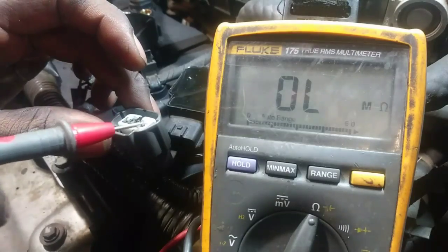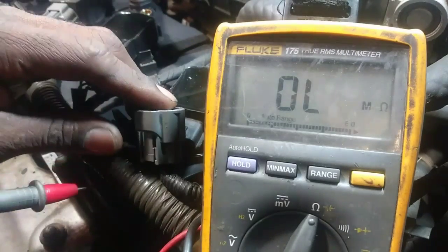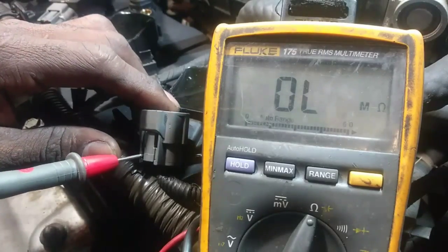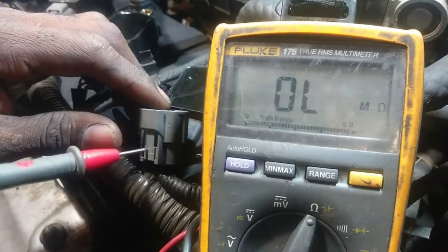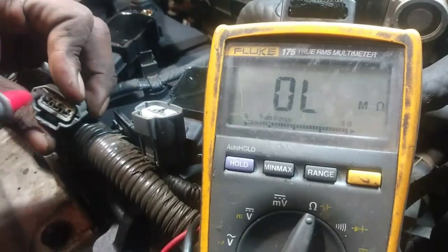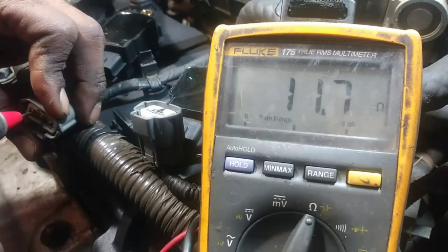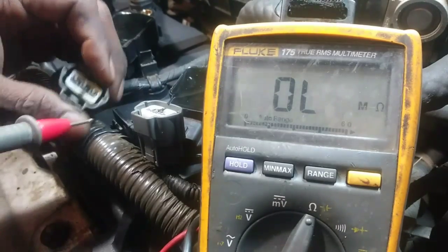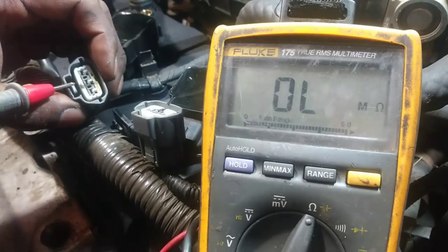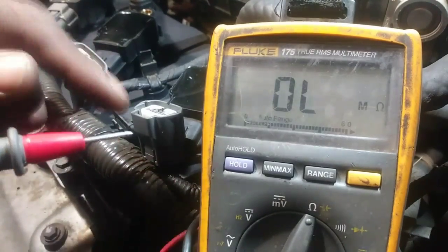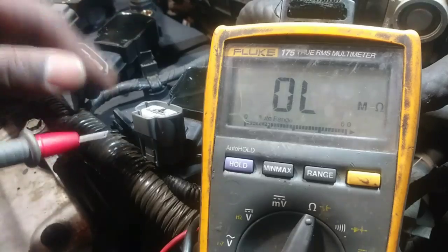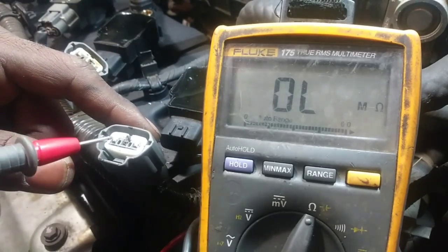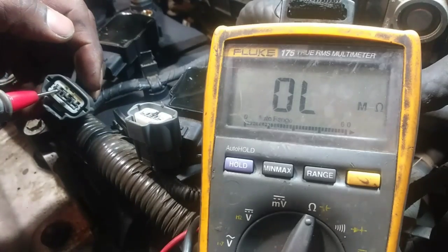So the car is simply going to need a computer, because that control signal comes directly from the PCM and back out here. So it's not grounded out totally to the point where there's low ohms. Now what I could do simply is take the computer, separate the connector from the computer, find the pinouts for this control circuit here, and do an ohm value and make sure all of them are in the same range.